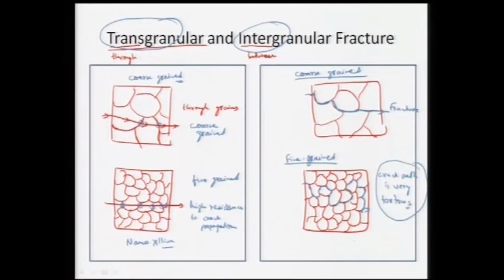In one more term, the toughness of these fine grained materials also will be very high, because now this fine grained material can also realign themselves and they can absorb certain shock. So, overall strain and the stress part can recombine synergistically to enhance the fracture toughness as well. So, generally fine grained material will have very high toughness in comparison to that of coarse grained materials as well.